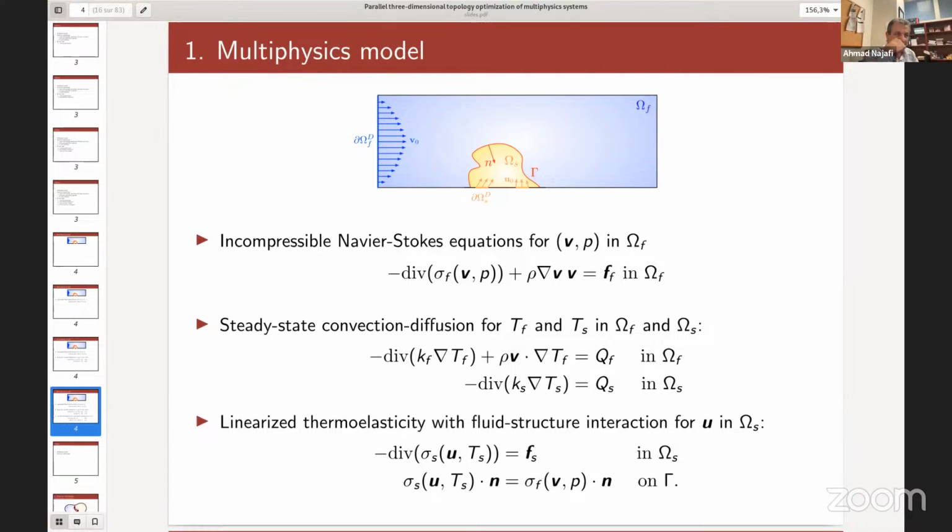Okay, so is your question related to why we choose an optimize then discretize approach and not the discretize then optimize? No, it is not my question. My question is, when you are remeshing, you have a domain on which you do all of your analysis. Then when your topology gives you a new geometry, you remesh your domain. So you have to map from your old analysis, even sensitivity analysis, to the new one. In this mapping, you will have some error, because it is some approximation. Could you comment on this?